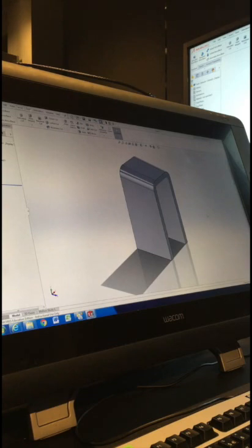But doing multi-directional, these are 2 separate lines. Yeah, you skip the offset part. So you go sketch, offset. The sketch looks alright. Select one of these lines, and now press OK. Oh, press cap ends. Change that to lines. Press OK. Yeah, because you didn't set cap it, so you can just draw a little line segment between them.